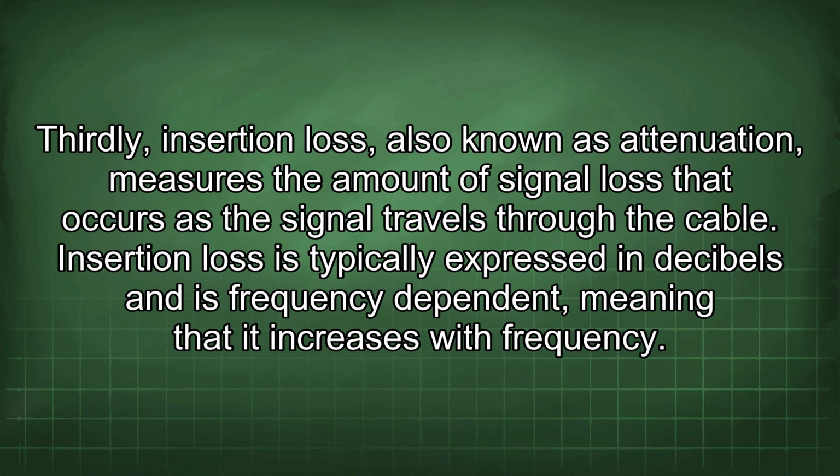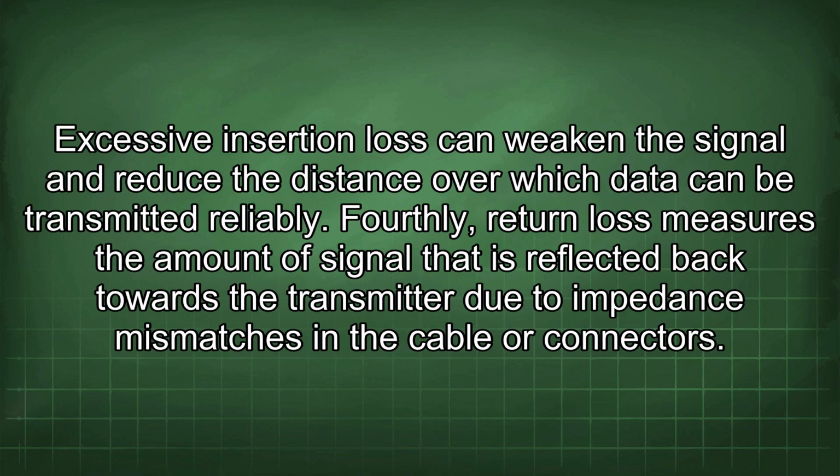Thirdly, insertion loss, also known as attenuation, measures the amount of signal loss that occurs as the signal travels through the cable. Insertion loss is typically expressed in decibels and is frequency dependent, meaning that it increases with frequency. Excessive insertion loss can weaken the signal and reduce the distance over which data can be transmitted reliably.